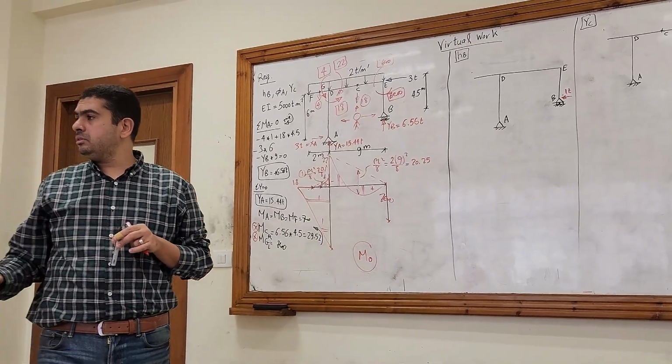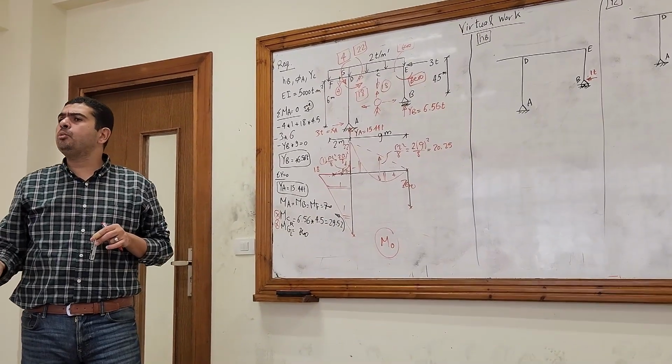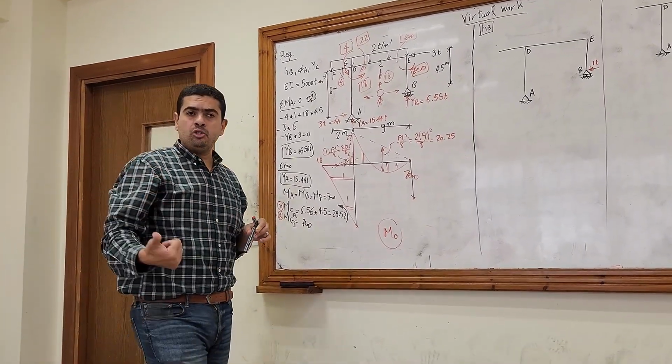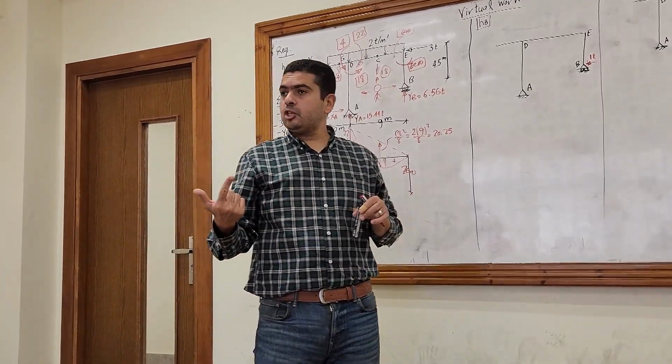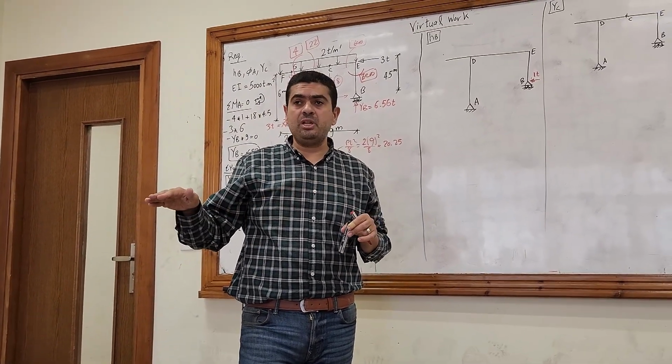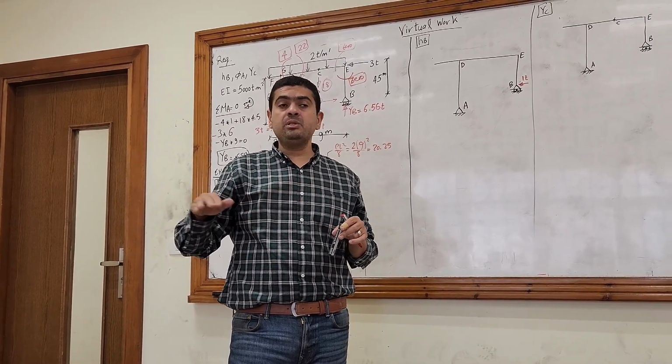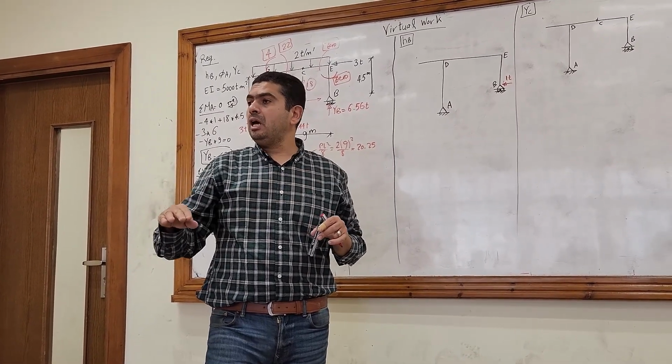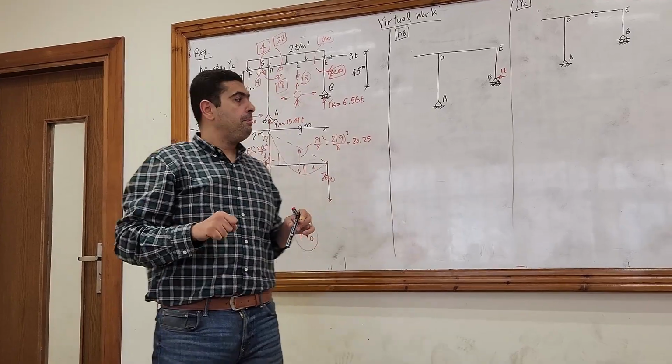I think you know this, right? What about the fixed support? It has a horizontal reaction, vertical reaction, and a moment. So no horizontal displacement, no vertical displacement, and no rotation at the fixed support. Okay?